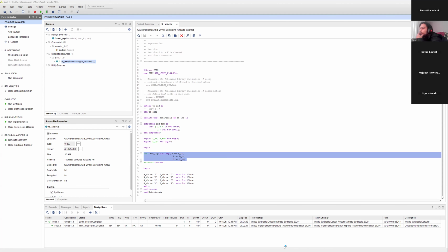So what we've done with the port map here is basically, this is just a name. We're just naming the port map. And then we're defining what we're creating the port map for, and then port map, and then we're connecting the ports, these things, to these signals that we have created. Now what we're going to do is assign values to these guys.